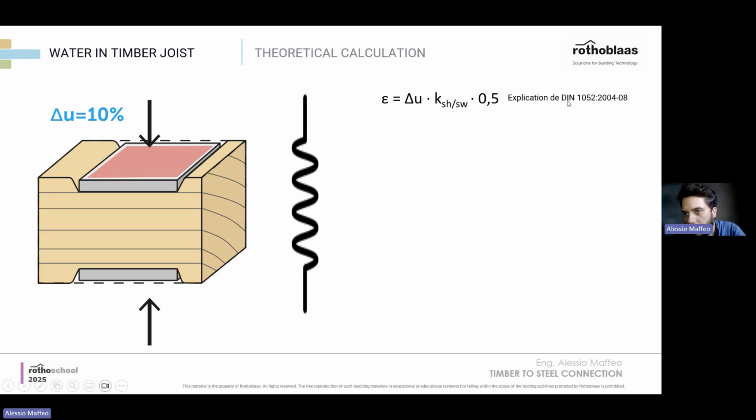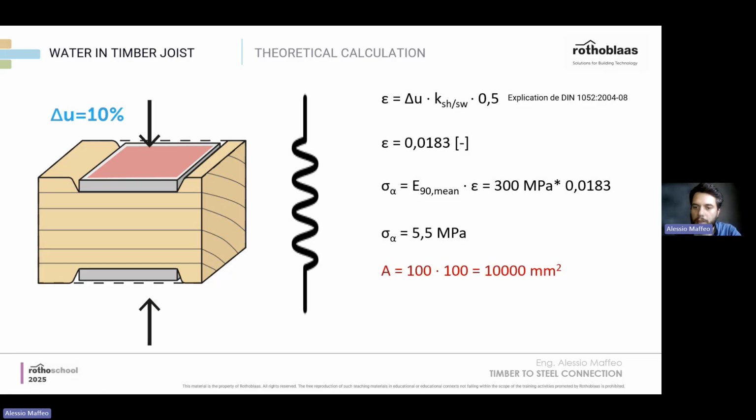Applying this standard, which is a standard for timber, we cannot replicate the whole calculation now, but you can maybe take a screenshot and follow more slowly. In theory, this piece of steel, 4 inch by 4 inch, on a piece of timber with a 10% moisture change, following this calculation, we get to this amount of pressure.